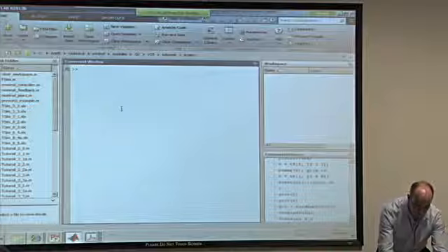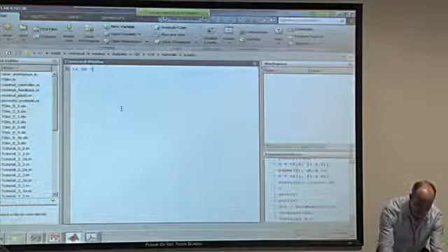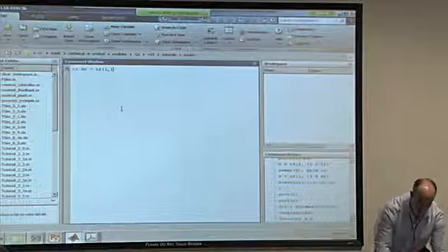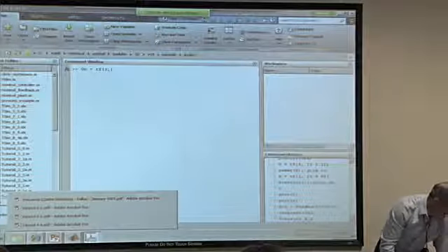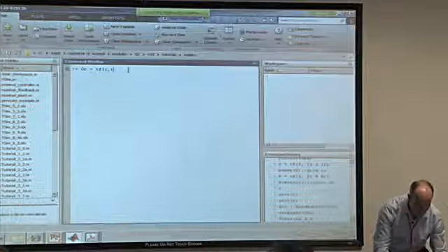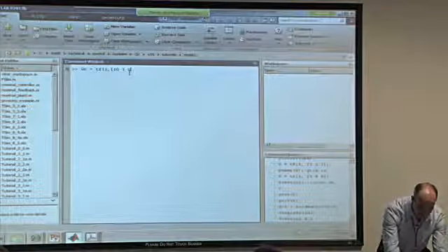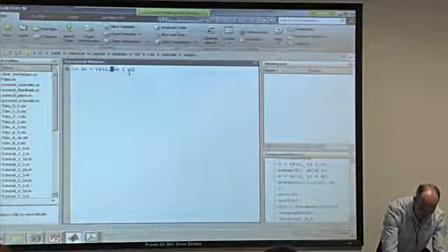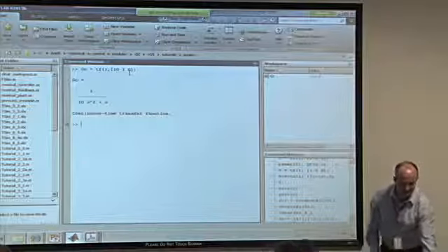The first thing to do is to create a model of the plant. So the continuous plant had the transfer function 1 divided by, I think, s times 10s plus 1, I always remember. So what we're going to do is call it 10s squared plus s, and then we've got a 0 in there like that. And I think that is the continuous time transfer function.